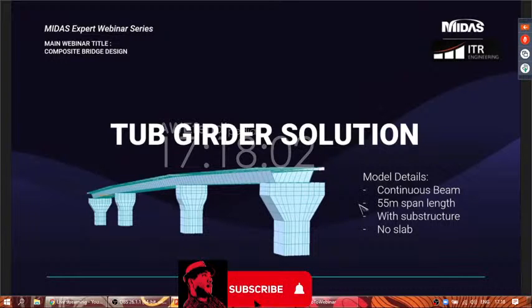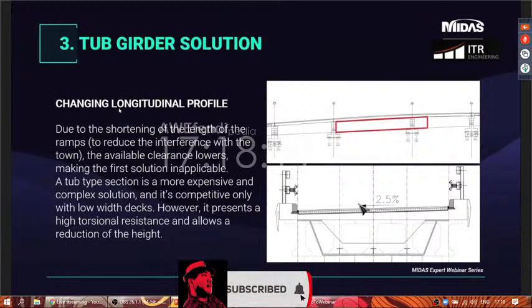The proposed solution was a continuity with a single tab section as main beam, still keeping a central span of 55 meters. Tab and box girders are more expensive and complex to realize. The difference between a box and a tab section is that the second one is open in the upper part. These kinds of sections have the advantage of a reduced height compared to the resistance, as well as a great resistance to torsion. Closed sections are economically viable only for reduced deck weights. And for our project, it seemed the perfect solution due to the limited space and the reduced dimensions of the bridge deck.